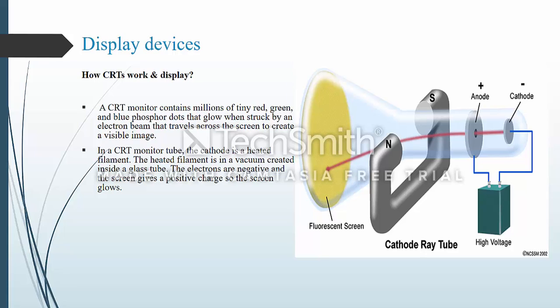Working of CRT. The heater element is energized by alternating current to obtain high emission of electrons from the cathode. The control grid is biased negative with respect to the cathode. It controls the density of the electron beam to focus the electron beam on the screen. The focusing anode operates at a potential of 1200 volts and the accelerating anode at 2000 volts to accelerate the electron beam.